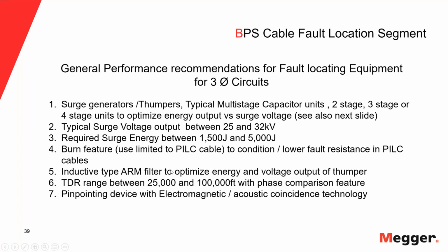All right, so going on here, when we go to the fault locating itself, to the prelocation, it's very clear an inductive type arm filter is absolutely preferable over a resistive type filter, because any resistive type filter will suck out the energy that the thumper provides. So I use a big thumper with a lot of energy, and then I put a resistive filter in, so I'm defeating my purpose. So it should be an inductive type filter.